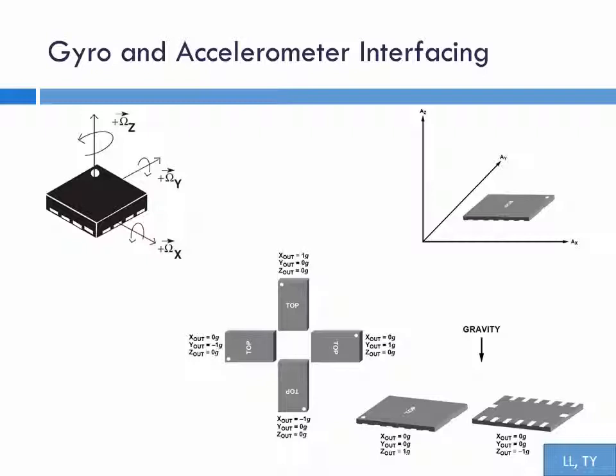In the case where axes are not parallel or perpendicular to gravity, measurement readings show the axis projection onto the gravity vector. So if the x-axis, for example, were to deviate by 60 degrees from gravity, the reading would show 0.5g. For more information, please refer to the demo code on the Digilent website.